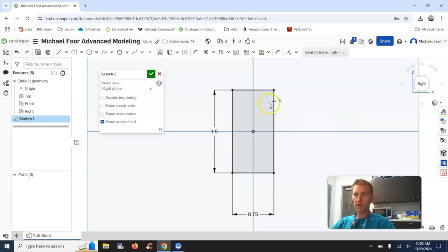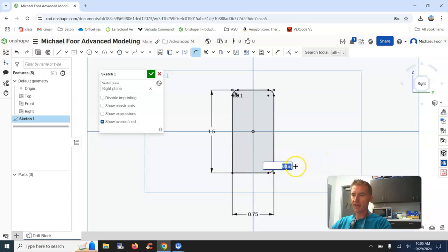Alright, so instead of doing our fillets in 3D, we're going to do them right here in the sketch. The way we do that is, this is your sketch fillet. This is just a different way to do it. There are normally a bunch of different ways to do stuff. So we're going to get that and just click on the 2 adjacent edges. I'll type in 0.1 there, do these 2, and we'll make that 0.1. You'll change the value. So we go ahead and click, then when the white box pops up, that's when we can change the value. And then 0.1, and we're good to go.